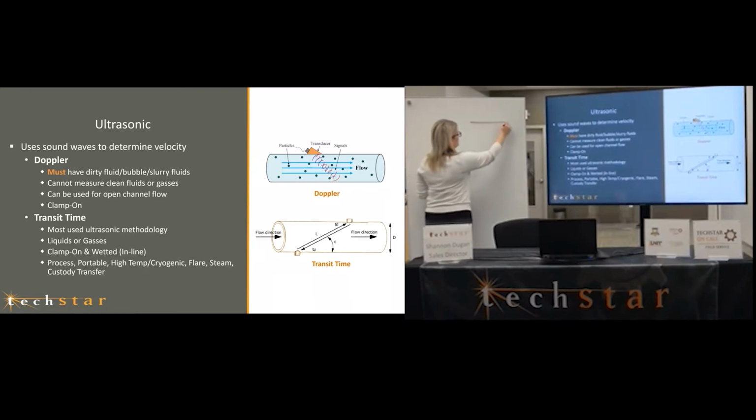So if you imagine this is your pipe, you have a flow going this way, and we're going to clamp some transducers on the outside. Now, regardless of whether it's clamp on or wetted, meaning transducers are actually seeing the process, the concept is the same. So each transducer is both a sender and receiver. As this one sends a signal, it's received by the downstream one, and it'll take a certain amount of time to get there because it's going with the flow.